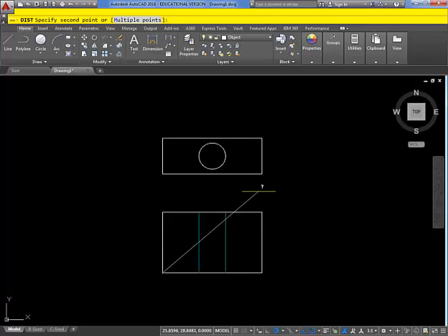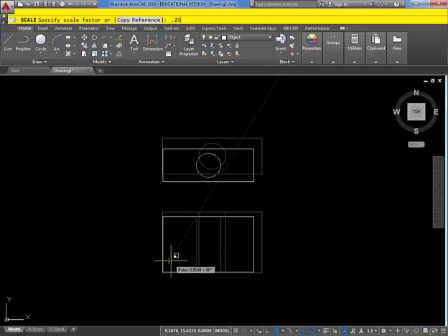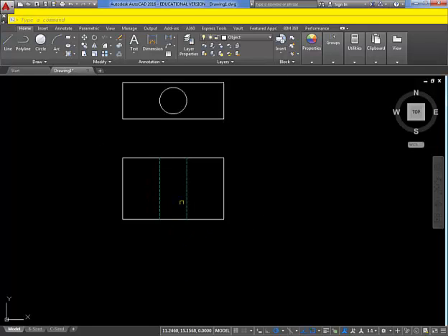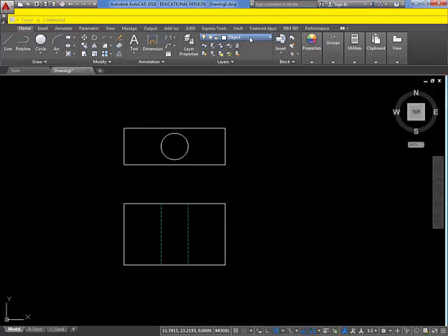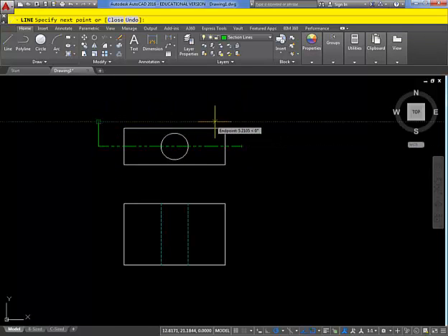Check how big a thing I drew here. A lot bigger than I meant to. Scale this down real quick. Okay, that's better. So this would be my top view, this would be my front view. The lines are hidden. The section lines layer is actually my phantom line. So if I wanted to create my arrows cutting through here, this is where you're going to get the phantom layer type.